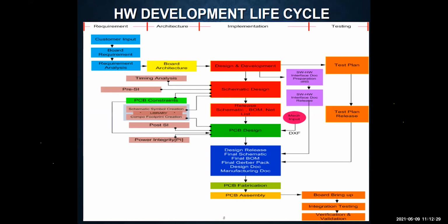Typically, you give your netlist and your PCB constraint file to the PCB engineer. So if you see the linkages to this schematic design: timing analysis, pre-SI, PCB constraints, PCB schematics, symbol creation, library, component footprint creation, okay. All these things will be part of it.